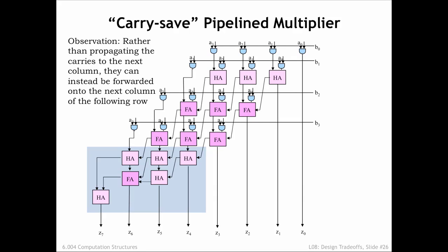In this schematic, we've redrawn the carry chains. Carryouts are still connected to a module one column to the left, but in this case, a module that's down a row. So all the additions that need to happen in a specific column still happen in that column. We've just reorganized which row does the adding.